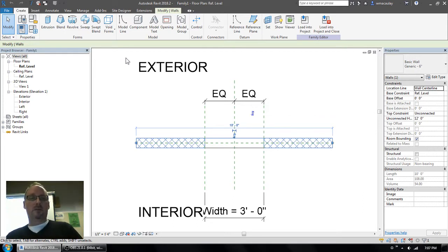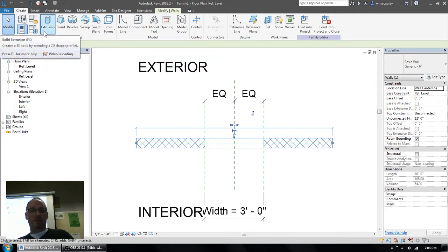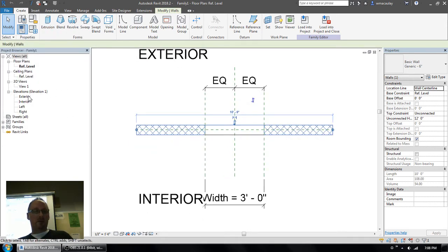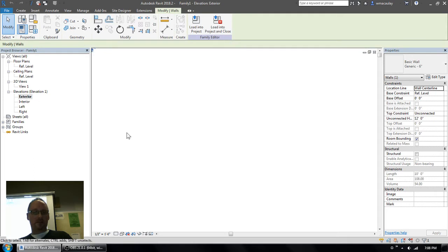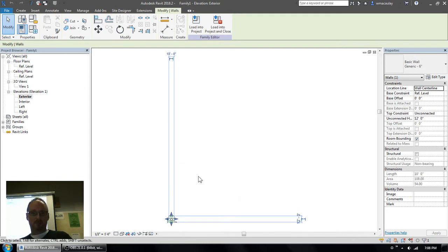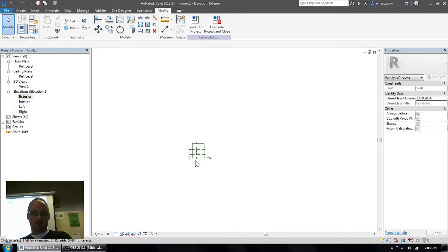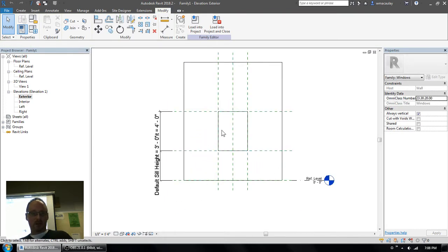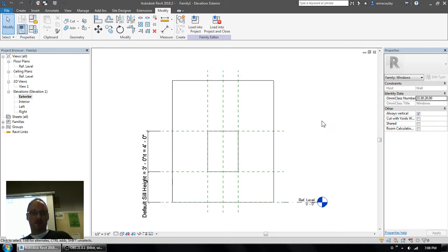And we'll get into which one you would use for the kind of geometry that you need to build. So with windows and doors, we generally can build everything with extrusions. So we've got the template here. There's a little piece of wall. I'm going to double click the exterior elevation. Now, for some reason, I can't see anything here, so I'm just going to right click and choose Zoom to Fit. Oh, that's weird. Okay. So I think you can choose ZX too. ZX would also zoom in.